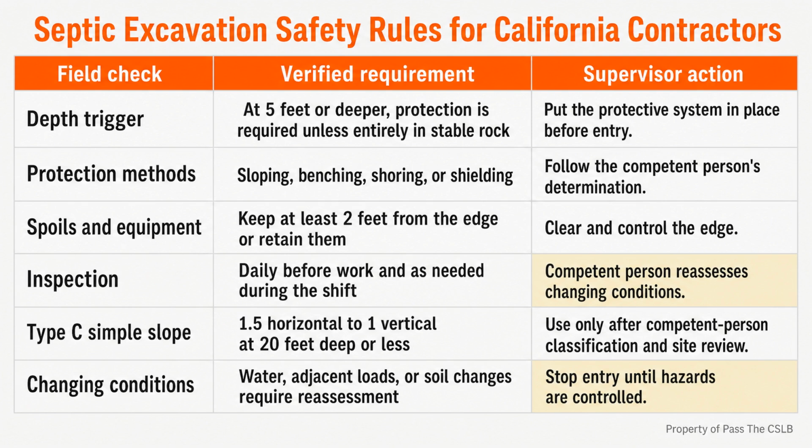Now I want to tie the site system back to estimating and scheduling. Before a price and start date become commitments, identify whether the property uses an on-site wastewater system, whether the existing system is functioning, whether added construction changes the expected load, which agency has jurisdiction, whether a percolation or soil evaluation is required, who prepares the design, and where the approved setbacks fall on the site. That is not septic design, it is scope control.